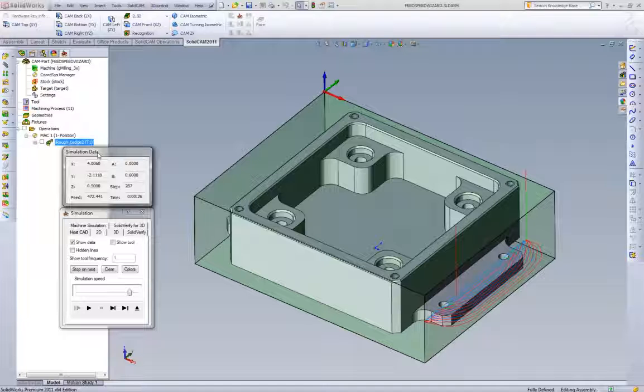But if we look at the fact that in iMachining we would be running a 3 thou chip load with a 4-flute cutter, if we double the 3, we're actually looking at 6 thousandths. So when you do the comparison between 2 flutes and 4 flutes, with iMachining, since we're controlling everything, your cycle times really aren't going to change by going from 2-flute to 4 flutes.